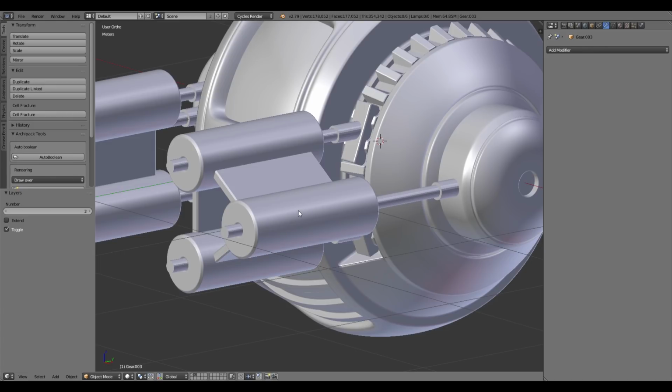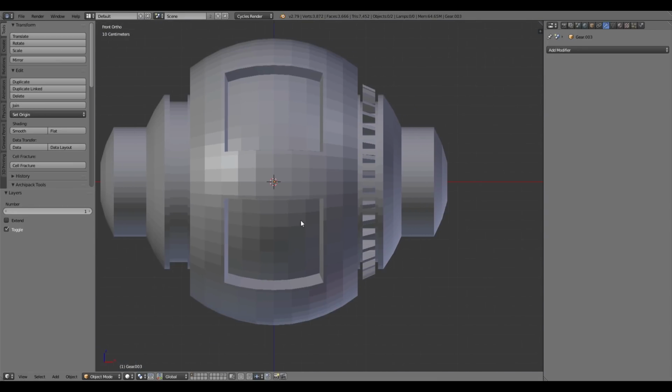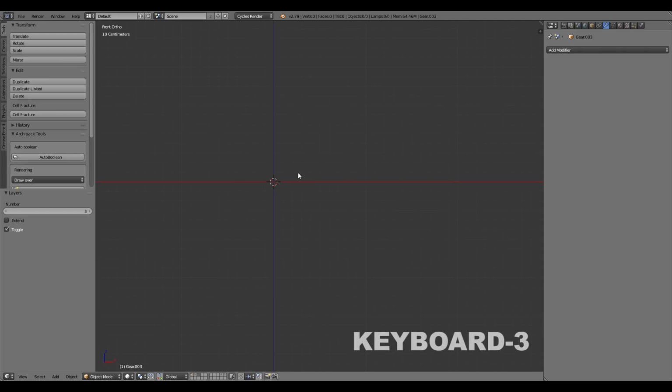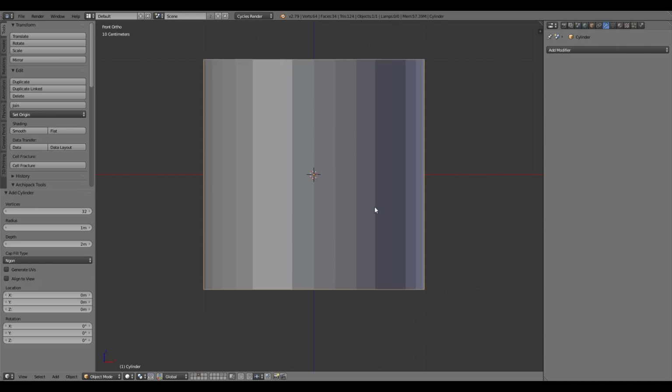And the one that I found the best for things that you have to repeat around an object is using things like the mirror modifier and the array modifier set to an object to create something that duplicates around a common pivot. So maybe what we want to do is model a gun on another layer and then bring them into this layer. So I'm going to go over to layer 3 where we've got nothing there, and I'm going to Shift A, add a cylinder.